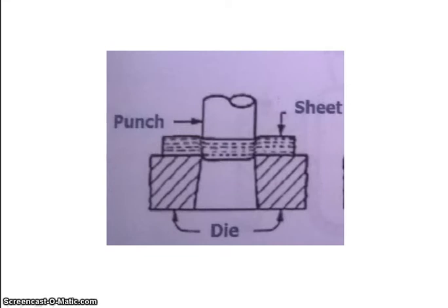Shearing is a generic term which includes stamping, blanking, punching, etc. When a long strip is cut into narrower bits between rotary blades, it is called slitting. Blanking is the process where a contoured part is cut between a punch and the die in the press. The same process is also used to remove the unwanted part of a sheet, but then the process is referred to as punching. Similarly, nibbling and trimming are a few more examples of cutting processes using the same principle of shearing.